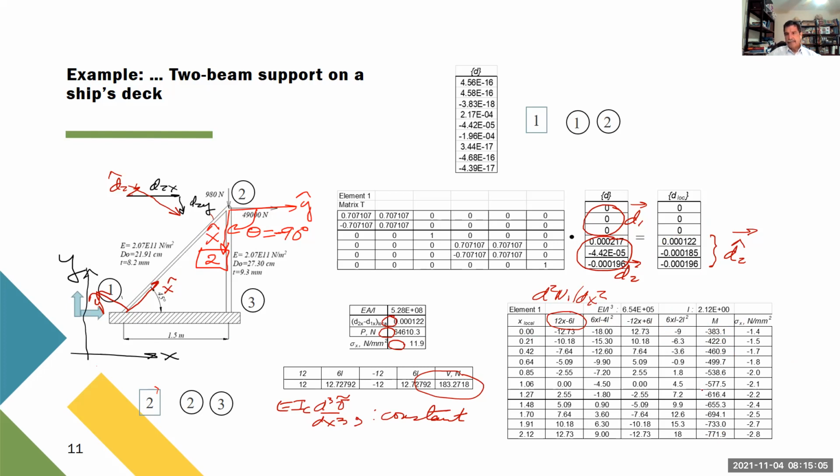And with this moment, we have the dimensions of the element. We can calculate the normal stress in bending, maximum normal stress in bending. And we see that the value is very small. So basically, bending is not much, okay? Basically, they are supporting axial force.